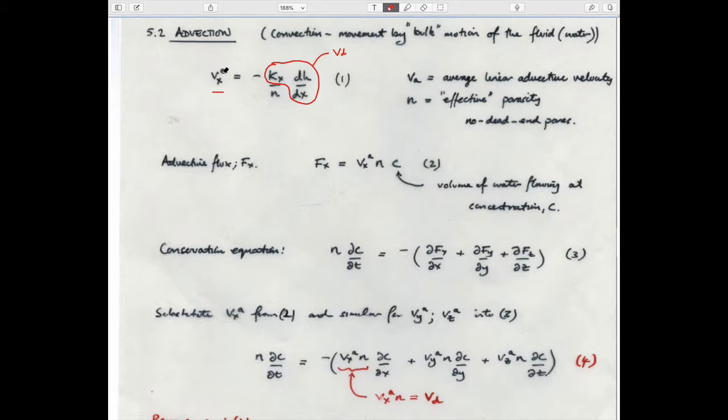If 99% of that pipe is closed off and it now flows at the same volume rate through now 1% of it, it travels 100 times faster. So that's really the difference between Darcy velocity, full pipe, and the advective flow, 1% left after it's closed off because of the cross-section area of the grains.